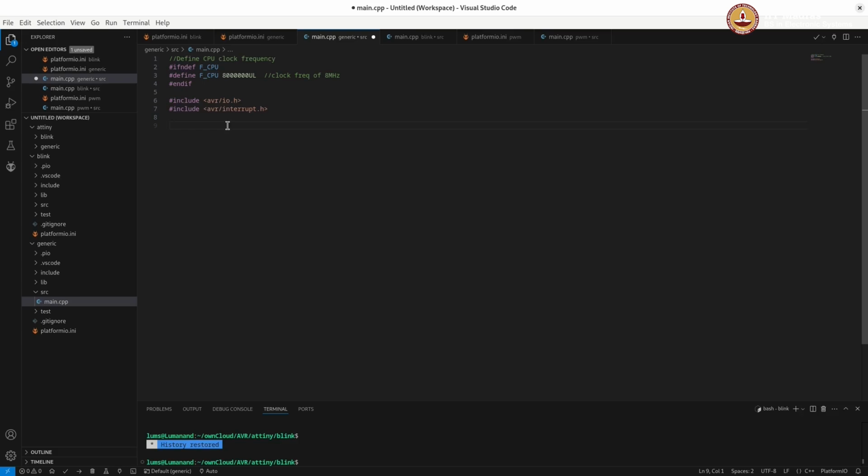Now, important, which normally people will fail to do, is set up the interrupt vector table. See, most of the programs you will use interrupts and you will have ISR routines. So I will set up the interrupt vector table, and this is something that you should not miss. Whichever the application, have the interrupt vector table set up. Interrupt vector table.